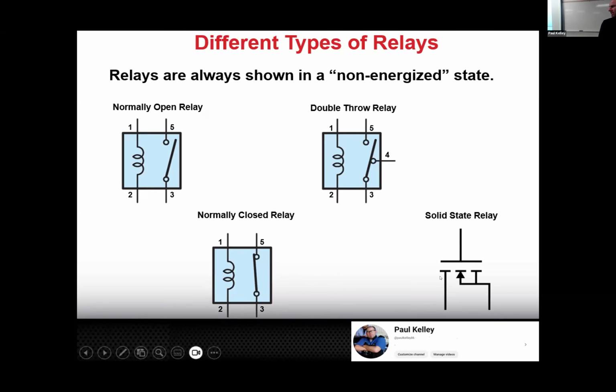Okay, and then what the heck is this? Solid state relay just means there's no actual moving parts. We're going to use that NPN or PNP junction to make continuity or not. More than likely, this is actually going to be a transistor. But sometimes transistors confuse techs, even seasoned, current professional technicians that are making double minimum wage can still be a little thrown off by transistors.